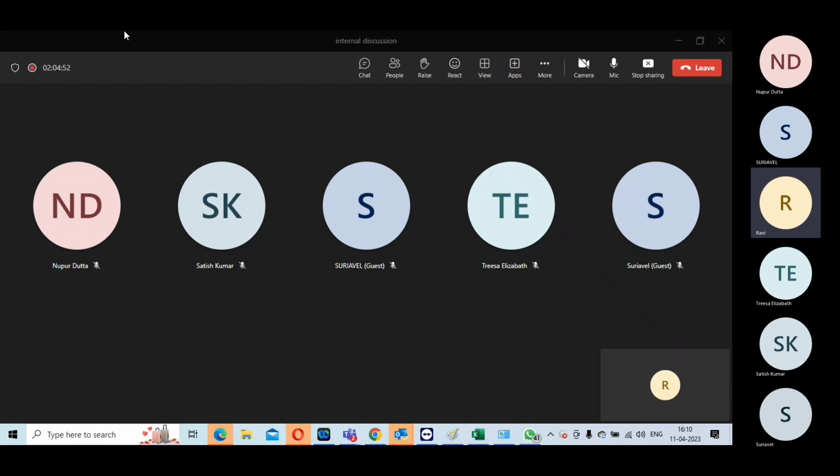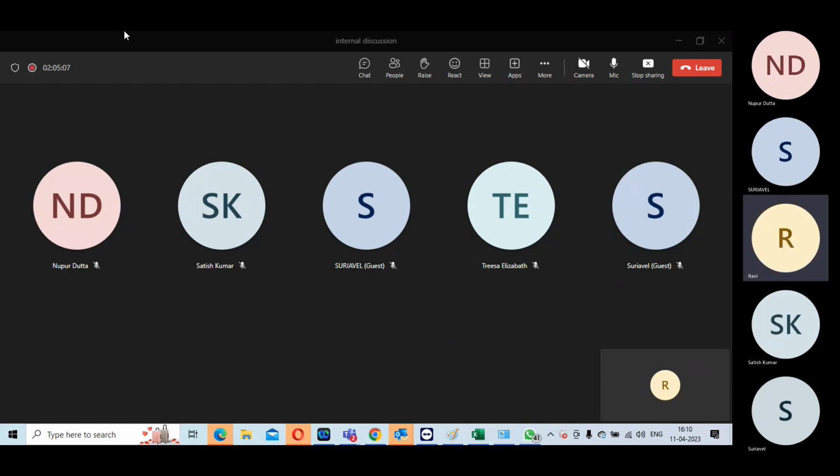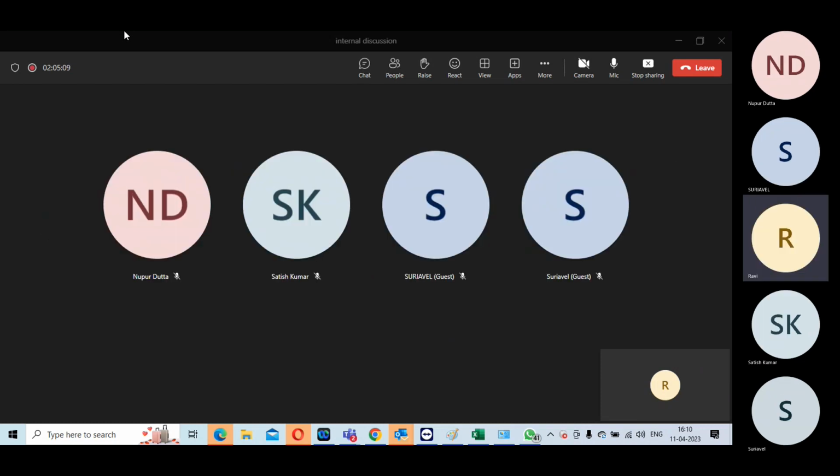If in one block you have 4 nanoseconds, and in this block you have 2 nanoseconds, that means you have a 2 nanosecond skew between these two blocks. How will the interface timing between these two balance? Then you will have to add 2 nanoseconds externally for this. You can add externally, but these are the things that you have to be very clear about.